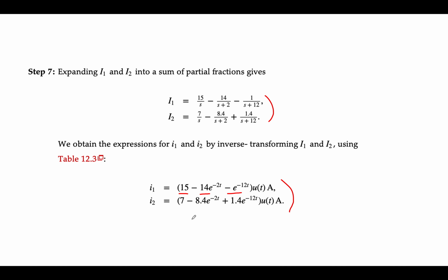So in this example, we can see there's not one time constant. There are actually two time constants. That's because you have two different inductors. Now, almost always, one of them will dominate, and it'll be the slower part of the circuit that dominates. The rapid part of the circuit, the transient effects go away pretty quickly.